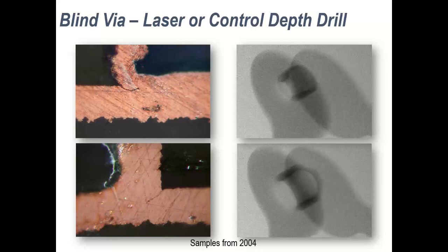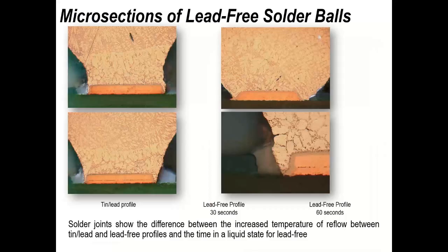So it just shows you that there's certain things you can see, but of course X-ray moves on every 6 months, so the quality of X-ray and detecting cracks is a lot superior today. But you can use different techniques to enhance what you're doing and looking at with a microsection.